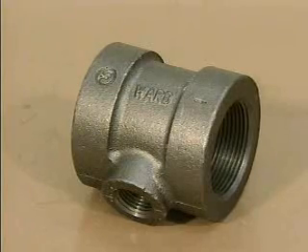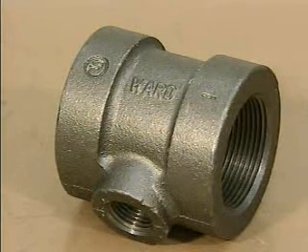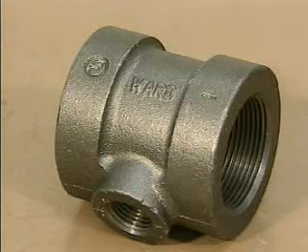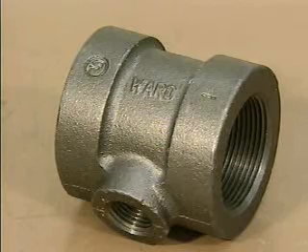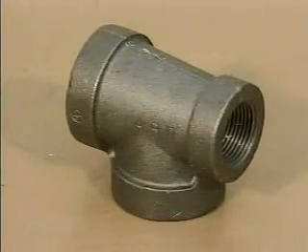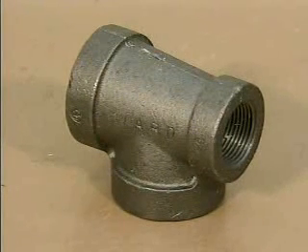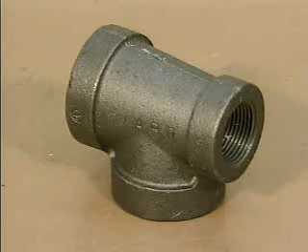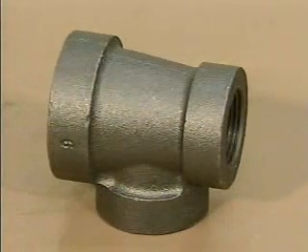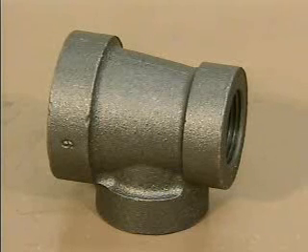T's come in a variety of designs. One common design is the straight run, reduced branch T. It is used to connect two same-size pipes in a straight pipe run to a branch. The built-in reducer at the branch connection reduces the flow of fluid from the run into the branch. Another common T design is this reduced run T. The reduced run T connects a pipe run to a branch. It also has a built-in reducer to reduce the flow of fluid from one of the run connections. In addition to connecting a pipe run to a branch, this reduced T has built-in reducers at the branch outlet and at one of the run outlets.